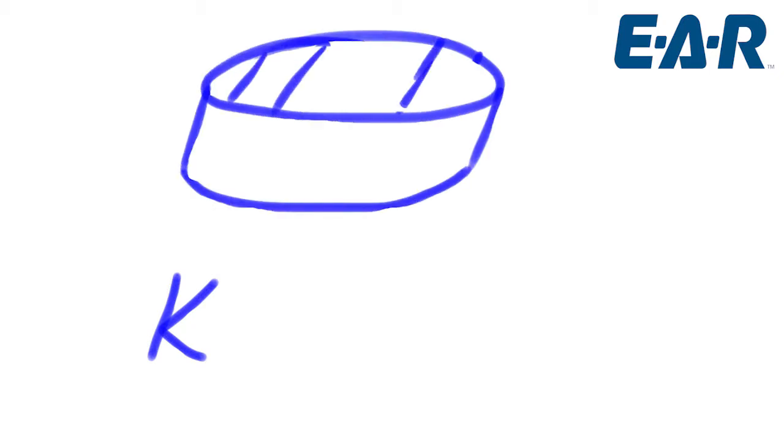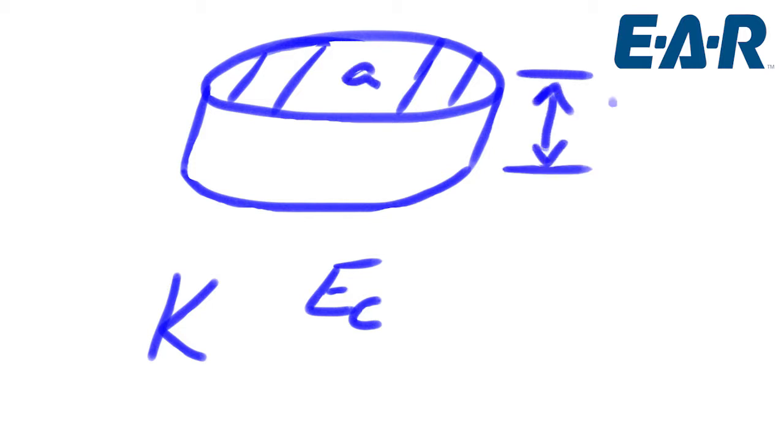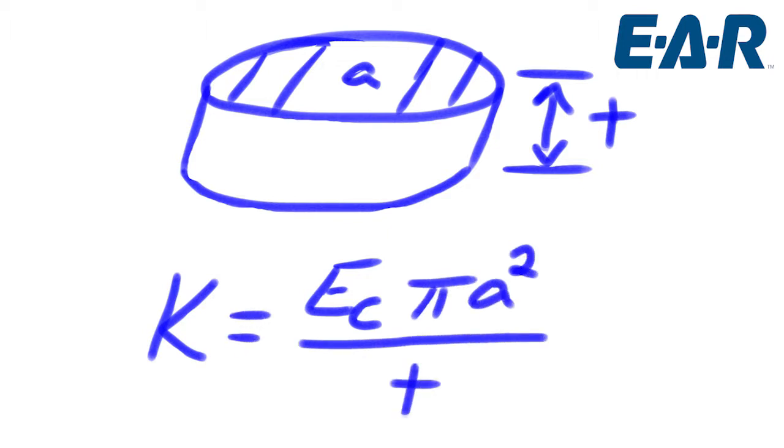Spring rate, usually denoted by K, reflects the back force of the mount under deflection. An elastomeric isolator has a stiffness that depends upon two factors: the modulus of the material at a given temperature and frequency, and the geometry used in the design. The following equation shows how to determine the spring rate for a simple elastomeric cylinder.